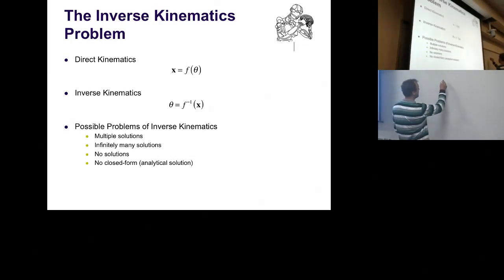Multiple solutions. That's a very simple thing which we'll demonstrate. Again, my little favorite two-joint arm, sitting here and reaching for a target which we put here. Now, if this arm has an appropriate range of motion, there is this second solution, which looks like this. So that is the second solution branch. There is no continuity between these two solutions. If I move this arm over here, then this end effector will go up, and then it will go down again. But there are two separate solutions.